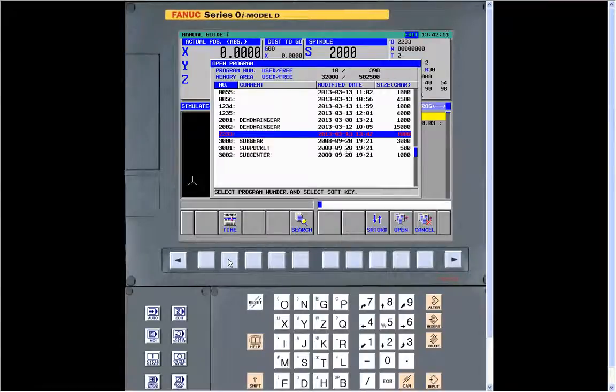If we go into our list and time to make that part, it's currently 8 minutes and 8 seconds. It's got 12 seconds of non-cut time, which is frankly pretty aggressive because, you know, you have to put times in there to tell it how long it takes to do a tool change. But again, you can use it to do time studies also.